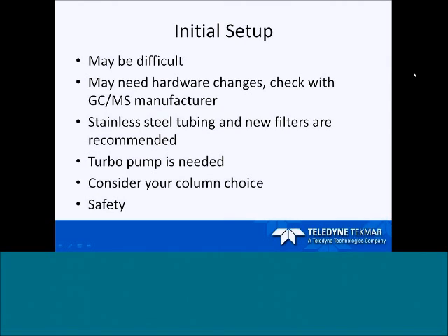And then again, safety. You definitely want to leak check and make sure you check with the GC manufacturer that it is explosion proof just in case something does happen or has a hydrogen sensor built in.